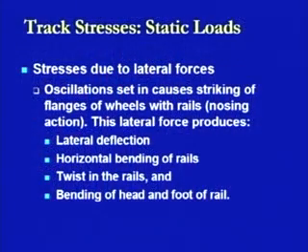Another one is the stress which is caused due to the lateral forces. In this case, the oscillations are set up and they cause the striking of the flanges of the wheels with the rails. Because of the small distance provided between the flange and the gauge condition, there is a lateral movement of the axle. When the flanges of the wheels strike the rail sections, that is the head or the side of the head of the rail section, that is what is known as the nosing action.